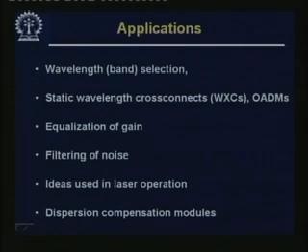There is a guard band between each of these operating lambdas, and the ITU-T has specified how much guard band you will have to have. So, you can have a large number of lambdas all grouped together in that same window. Now, a band out of that, that means a bunch of frequencies, you can select instead of just selecting only one frequency. So, that is wavelength band selection.